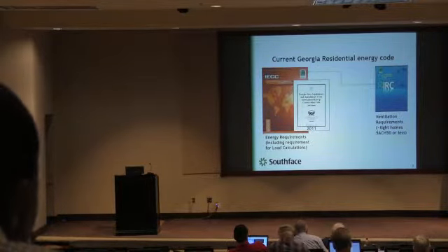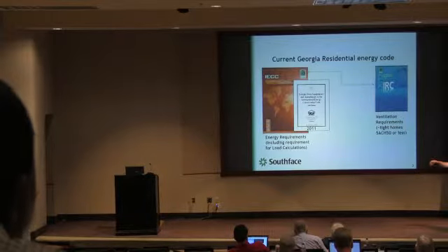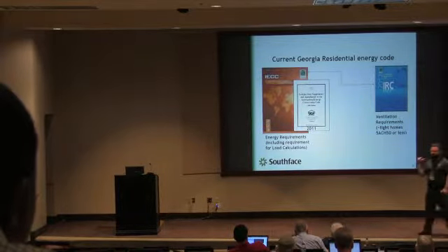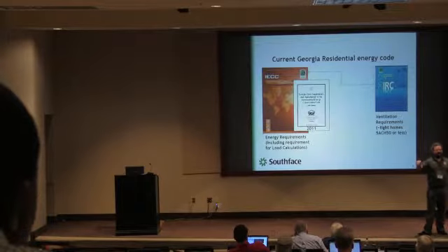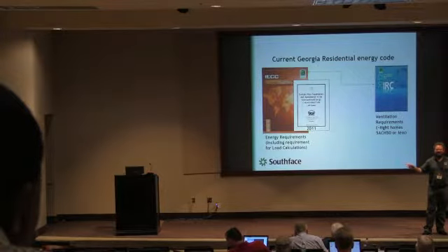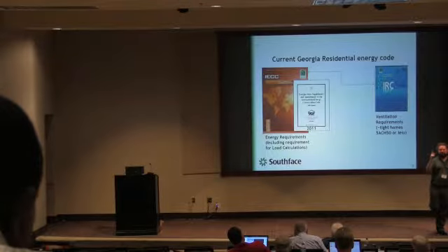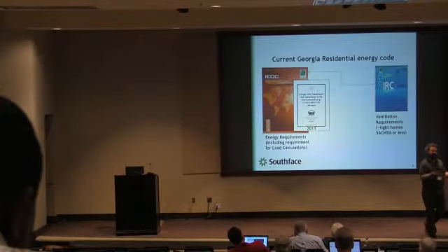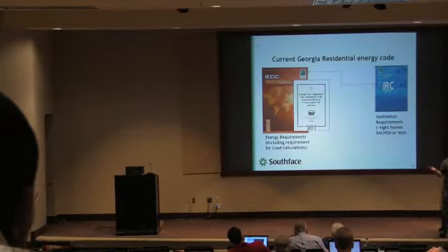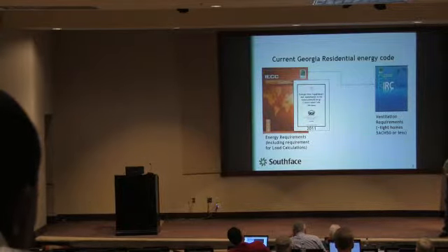And on the residential side, it not only says do a load calculation, it says you have to size to it. In the commercial world, it says the engineer has to do a load calculation, but then they basically get the choice to ignore it or pay attention to it. That's in the commercial world. In the residential world, it's clear: do a load calculation, size to the load calculation. So that's the law. Now, I don't know if people are getting sued for bad load calculations. Probably not a rampant issue, but it is the law.